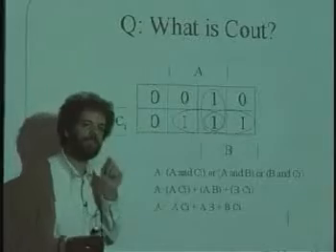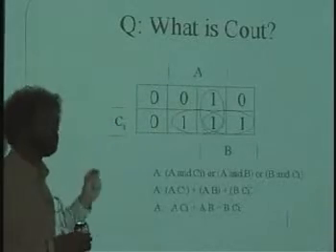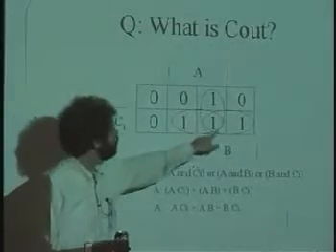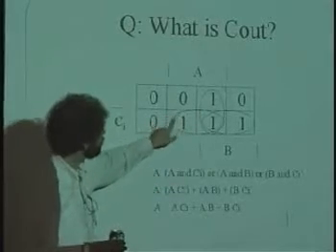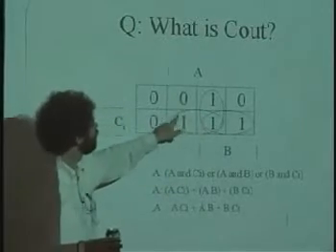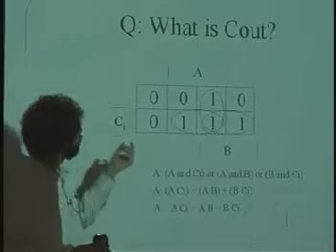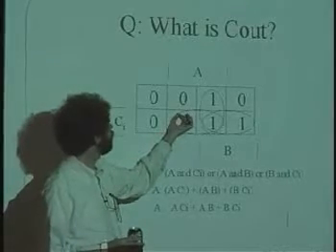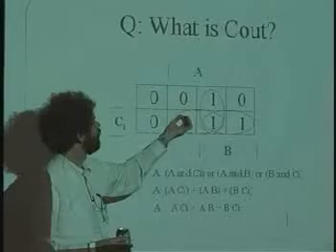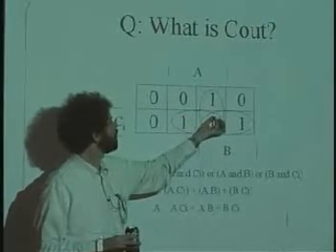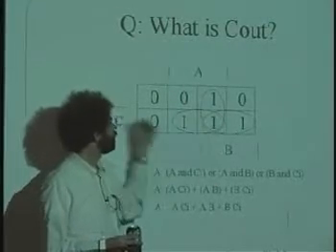Now what does it mean to circle both of them and to make only one product term out of this oval here instead of the two product terms that I used to have? Let's only pay attention to this one over here on the left. Well, it used to be that I had one term that was dependent on A, B bar, and C sub I, and another term that was kicked off by A, B, C sub I.